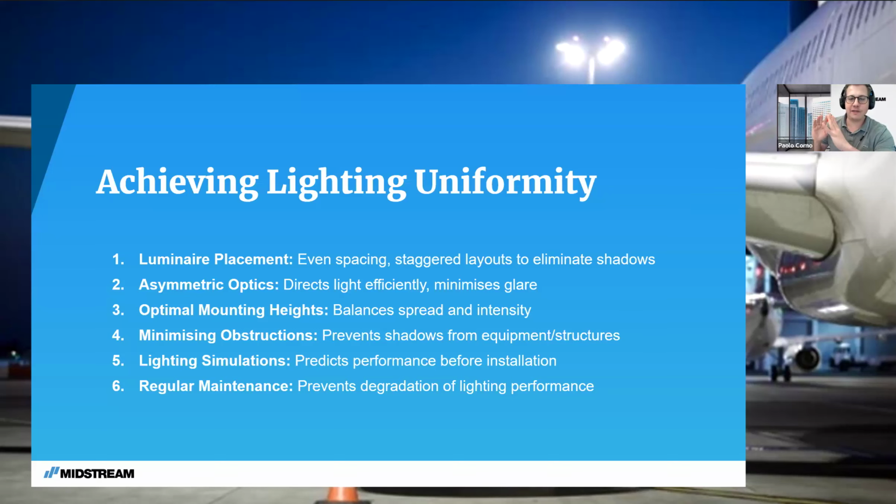If you didn't have this requirement, you could have perfect light on the ground. Then airplane comes in, and you only light the first 10 meters of the fuselage, and where you actually have to unload the baggage is pitch black. So this allows you to be able to work on all the parts of the airplane, whether it is for baggage, refueling, any sort of maintenance, even with the visual checks on the engines. That's where the uniformity on the vertical plane comes into play.